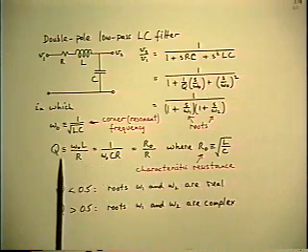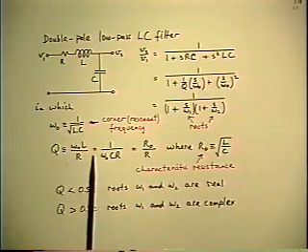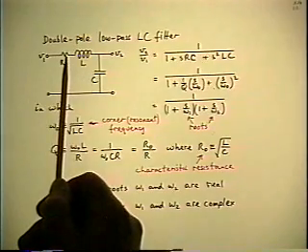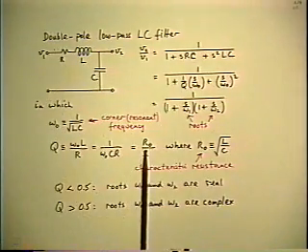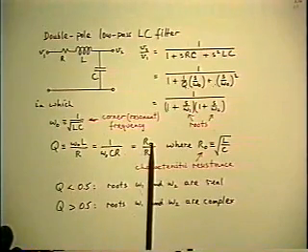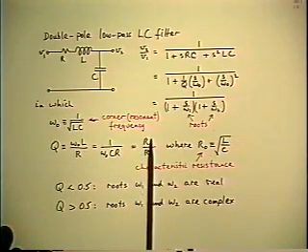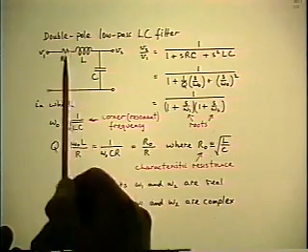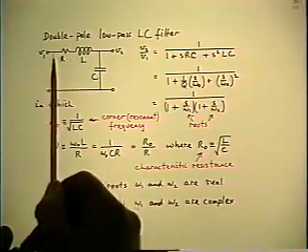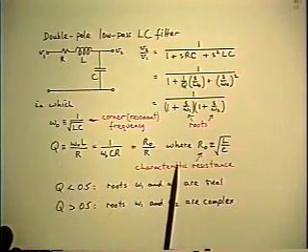The third parameter, the Q, is the only parameter that gets the real resistance into it. And you see by this simple definition that the Q factor is the ratio of the characteristic resistance determined by the L and C to the actual resistance of the circuit. That's the only place the R gets into it.